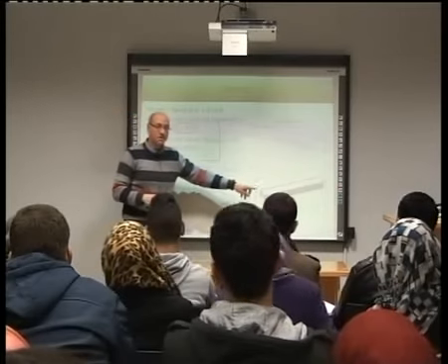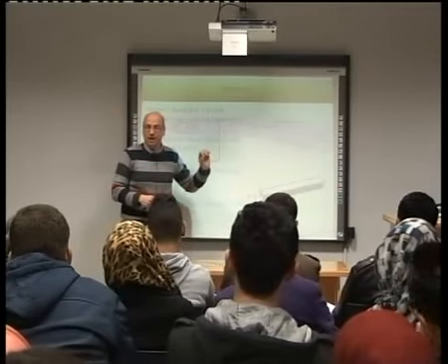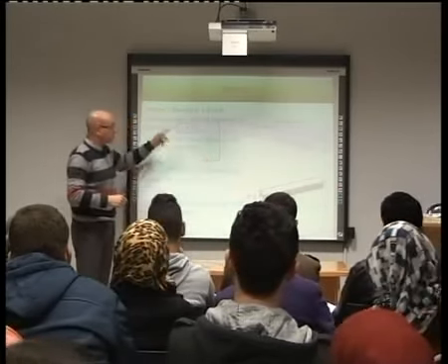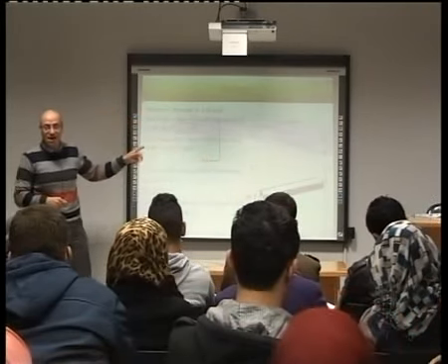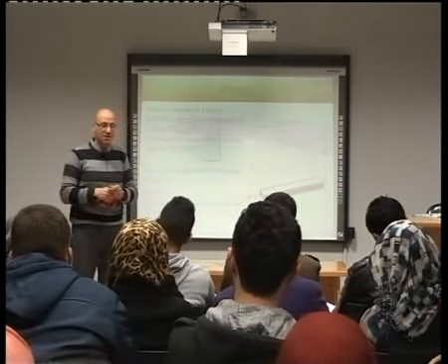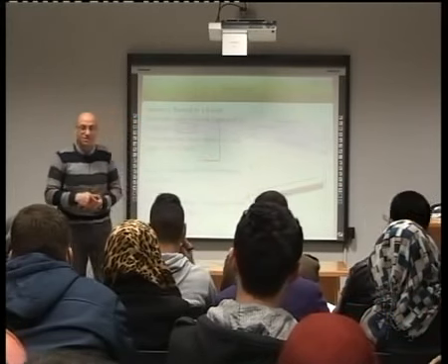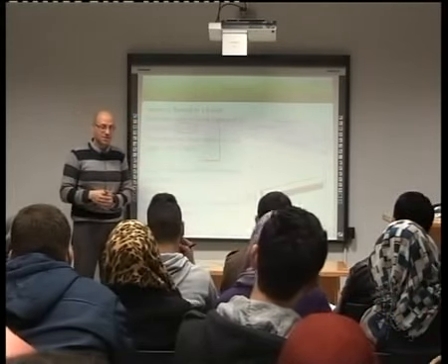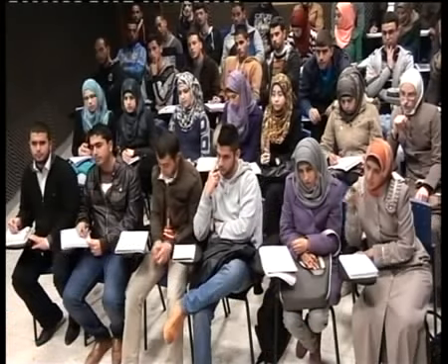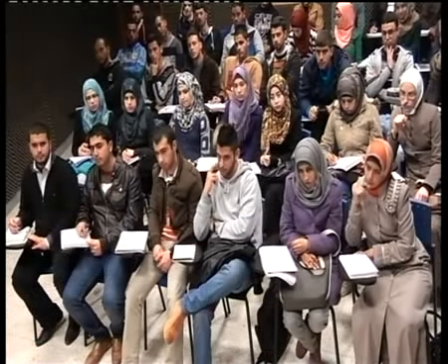In the pressurized systems, we don't really care much about the slope. So why is this question giving us a slope value? Why? To calculate delta z.